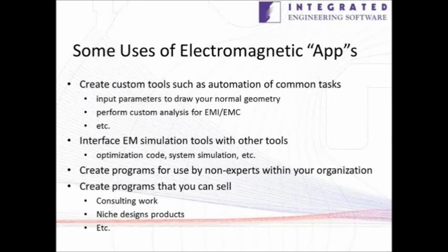You can also create EM simulation tools that interact with other tools, and that's where an API is really more powerful than simply a scripting environment that you might have within the software. With a script, yes, you can do the things I discussed above. You can create a script that will prompt you for parameters to draw your geometry, for example. But let's suppose that what you want to do is to use the optimization code in MATLAB in order to keep modifying your geometry.